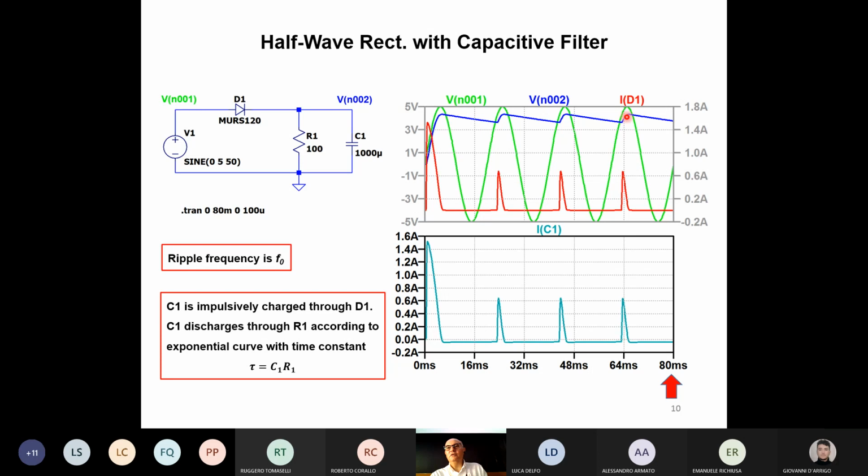If you see the voltage in the resistor, you can understand that this current is almost constant. There is a big improvement in the shape of the voltage across the resistor just because we added the capacitor. Now the voltage in the resistor, and the current in the resistor, is almost perfect. There is still some ripple, but it's much better than it was before without the capacitor.